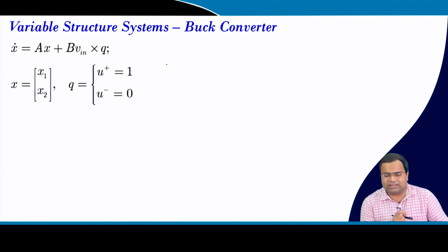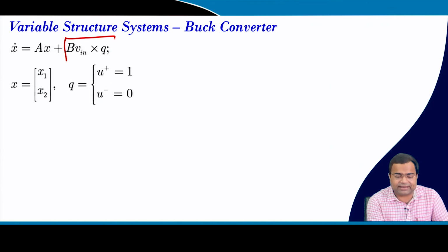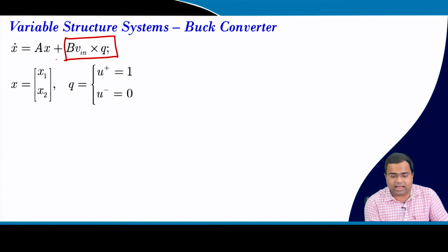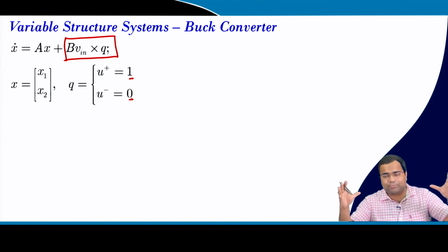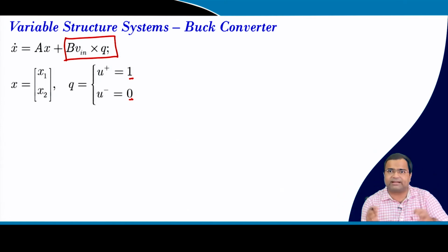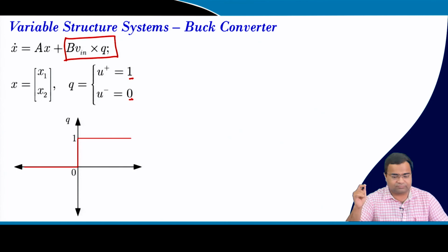So, this starts with our buck converter that we did, where this creates our discontinuous vector field, which can take either 1 or 0, and that shifts the operating point, but at the same time the vector field gets shifted here, right. That means in the phase plane, at one particular point the direction of the vector field will be different for two different switch states.